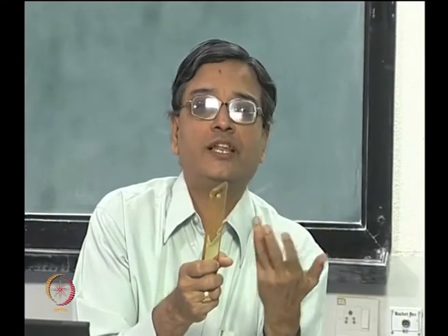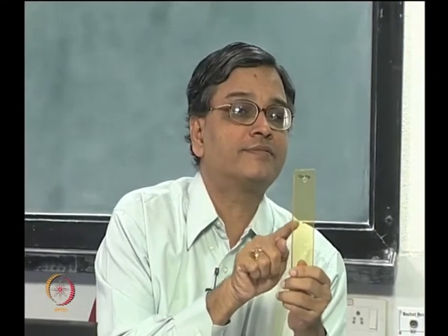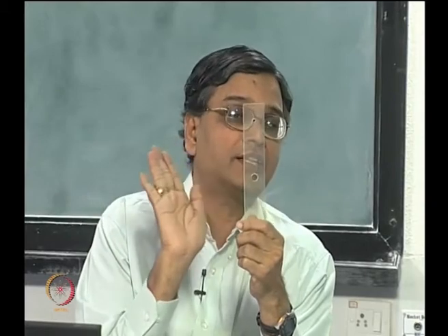You all learned, in one of your design courses, when I have riveted joints I have a series of holes. So, the idea here is, as an analytical method, you have been able to find out how the presence of a hole influences the stress field near the hole. You are able to get an analytical expression, and this will be a function of x and y. So, if you plug in x and y, you will be able to find the solution at every point in the domain, okay, which is not the case when I take a finite geometry. This finite geometry is not possible to solve by theory of elasticity.